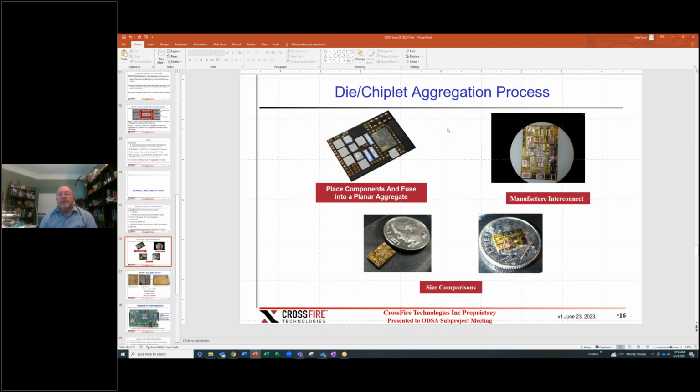And that's where it gets interesting in things like die bonding, right? Because even the pitches there at die bonding are limited to the micron range right now. But we feel like going 3D and mounting a die like that, we can get down sub-micron pretty easily. It's going to take the I/O on both die to make that happen. But it's very, very feasible.